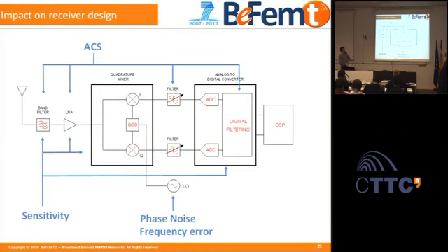The receiver has the opposite block diagram to the transmitter. Here the direct conversion architecture is used, where the signal that comes in at RF frequency is translated directly to a baseband signal with the help of the local oscillator, which has to be at the same frequency as the transmitter in order to tune the signal perfectly.